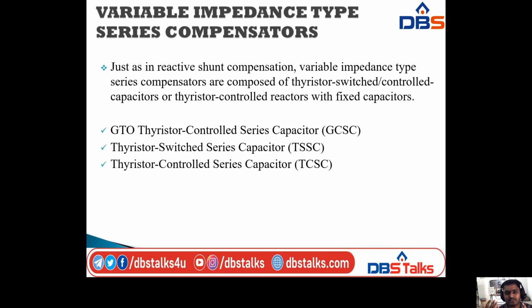We have three types of variable impedance step series compensator. The first one is GCSC, the GTO thyristor controlled series capacitor. The next one is the thyristor switched series capacitor, known as TSSC, and lastly we have the thyristor controlled series capacitor, that is TCSC.